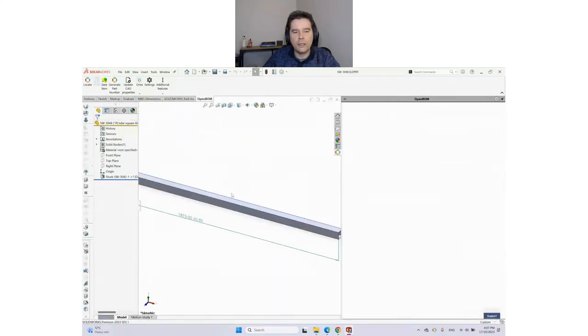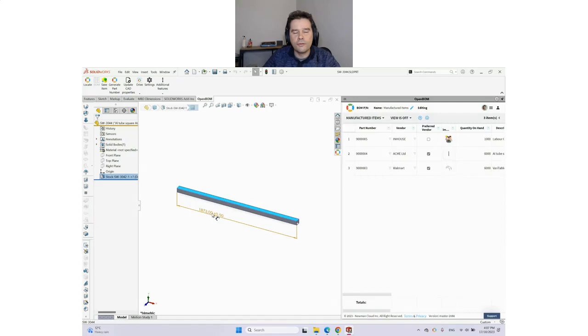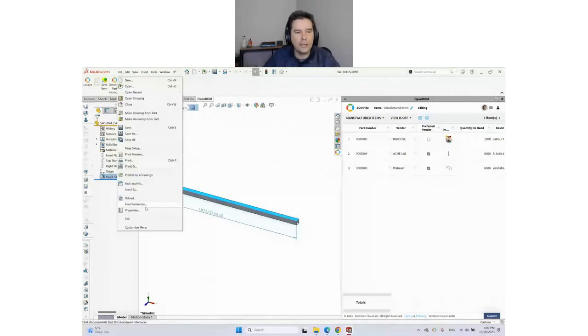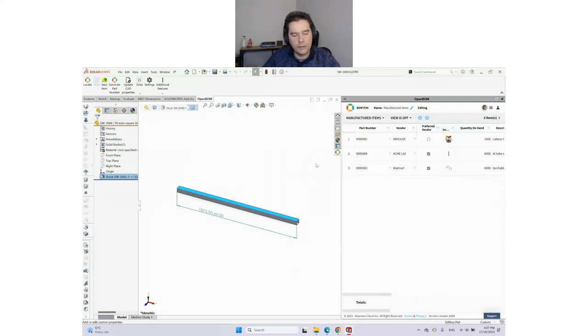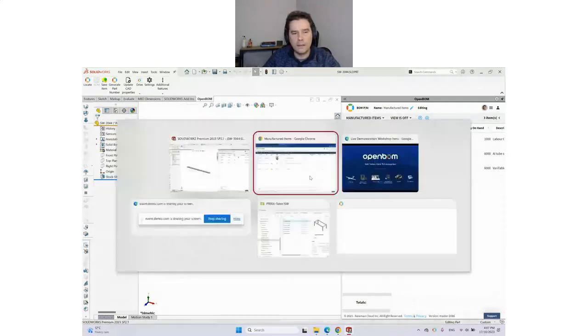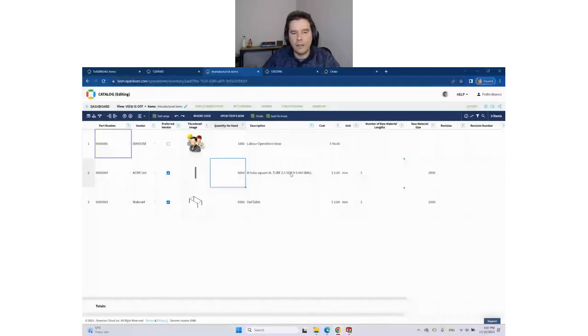So in this example, what we are doing to calculate this is that some CAD programs do have a feature to send the quantity of a material as length, for example. In this CAD system, SolidWorks, you can select that the BOM quantity that you send is the length. So this is how you are getting the full quantity of material for this specific example. And then you can calculate quantity on hand, and you can consume in meters in a very easy way.